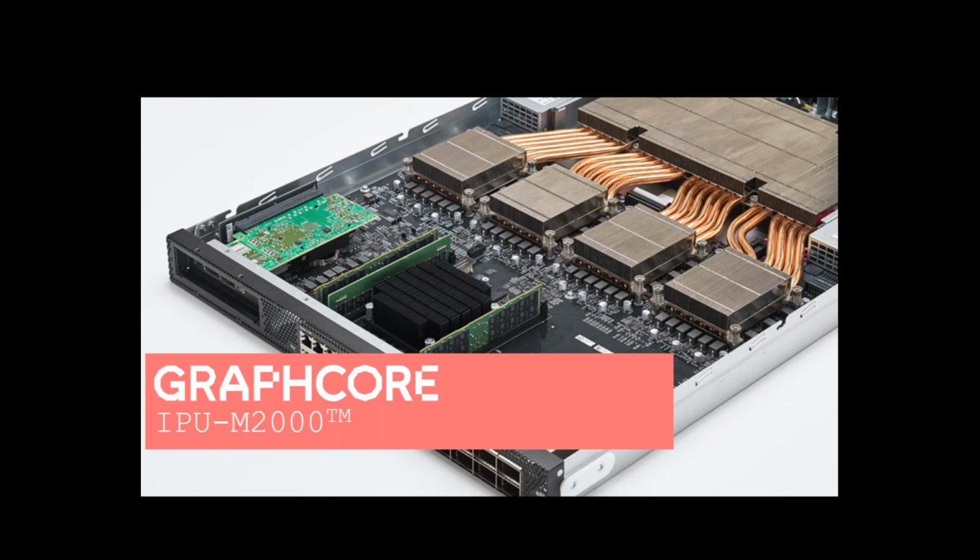So we look at a very large die, 823 square millimeter die, but we look at sub-die within each die at the scale of about 1,500. We've got subdivisions within those as well. So we're looking all the way down to the individual ring oscillators that describe the transistor performance in TSMC. We're looking at standard yield metrics, and Matthew will show you a bunch of those.